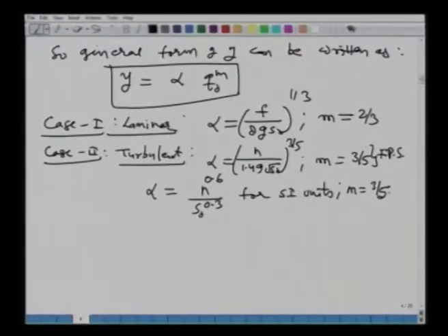All right. So, you see that this way what we have done is we have taken a control volume approach of the overland flow in which the rain is falling, infiltration is taking place and the overland flow or the surface flow is taking place. With that we applied the continuity equation and the momentum equation, then we combined the two to find out what will be the flow depth and velocity. All right. This we have done for both the laminar and the turbulent cases.